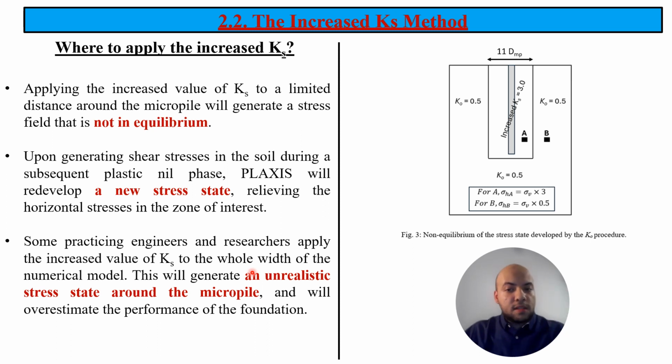To overcome this limitation, some engineers maybe intentionally or unintentionally apply the increased value of Ks to the whole width, but this is wrong, and it will generate an unrealistic stress state around the micropile and may lead to overestimation of the foundation capacity.